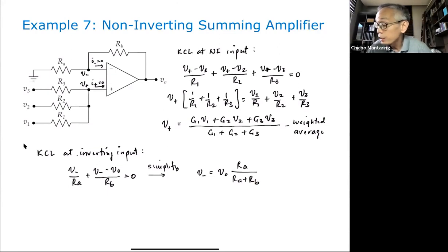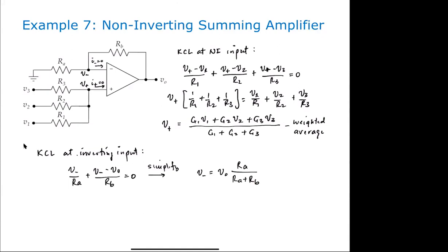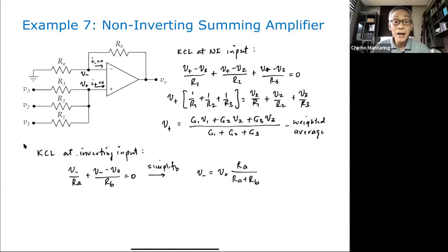Joseph, do you recognize this equation? Voltage divider po. Yeah, that looks like a voltage divider, right? And if you think about it, it is a voltage divider, no? Kasi kung zero itong current na to, ibig sabihin naka-series lang yung RA at saka RB. If this current is equal to 0, these two are in series, and therefore this voltage V sub O will just divide between RB and RA proportional to the resistance value. And so this is your voltage divider equation.